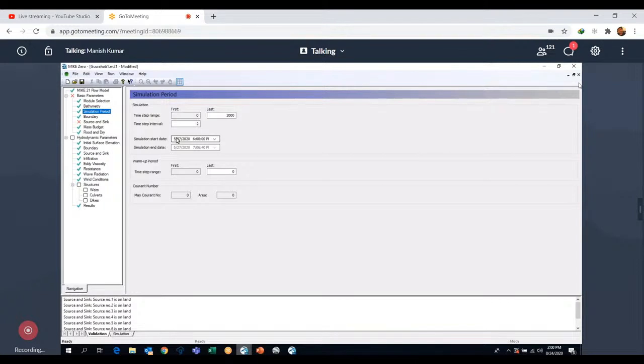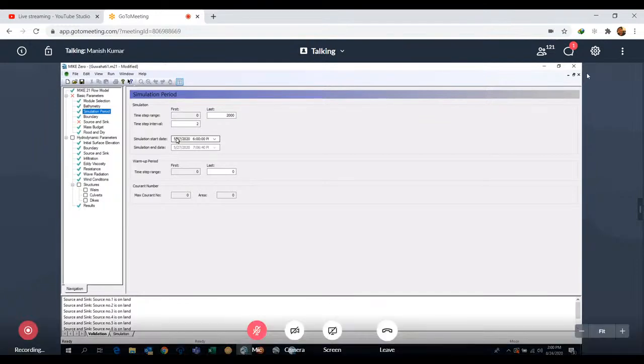Then how much time will it take to reach grid 2? 1 second. So in 1 second it will reach from grid 1 to grid 2 if your grid size is 1 meter. Now if you run your model every 2 seconds, then what will happen? The water from grid 1 will reach grid 3. So there will be no calculation for grid 2 and your model will stop.